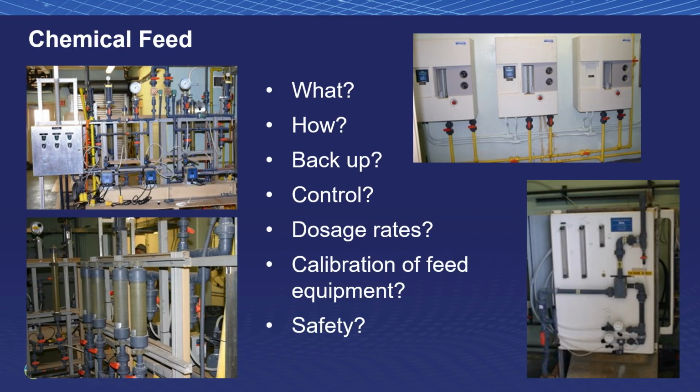Chemical feed rooms. The chemical feed rooms should be well marked, clean. Your chemical pumps shouldn't leak. And I haven't yet seen a chemical pump that's pumping caustic that doesn't leak. Maybe a brand new installation with a peristaltic pump, maybe. But generally, it's pretty hard to keep caustic inside a delivery line.